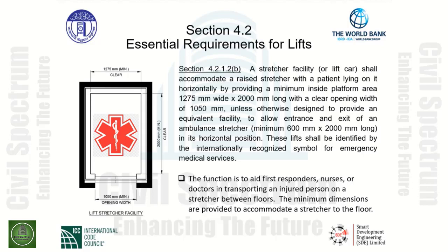As indicated in the graphic, we can see the minimum interior dimensions that must be maintained when a stretcher facility is required for the lift car. The function is to, of course, aid first responders, nurses, or doctors in transporting an injured person on a stretcher between floors. The minimum dimensions are provided to accommodate a stretcher to the floor.